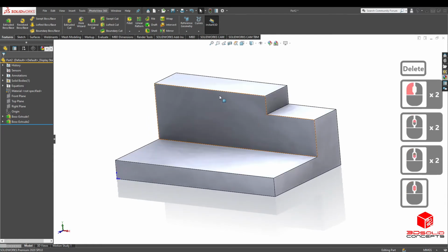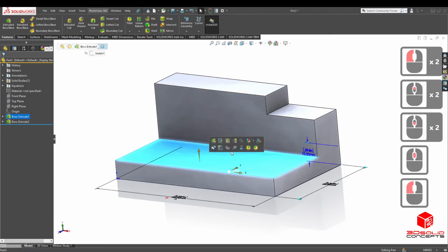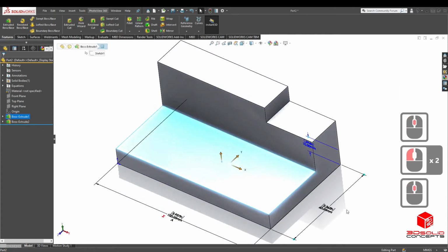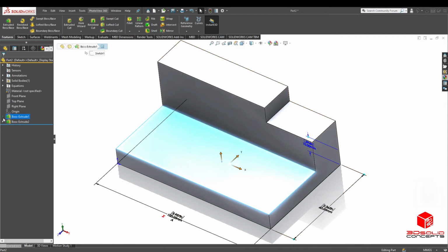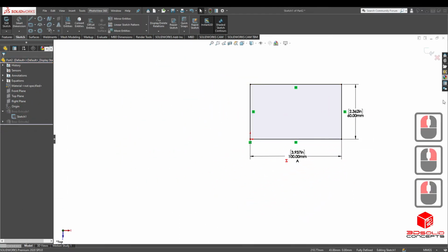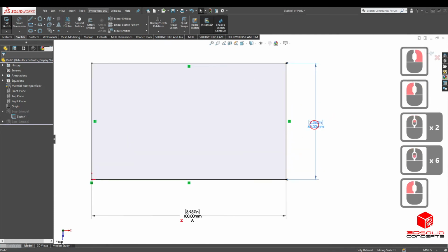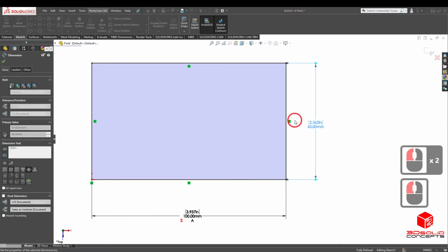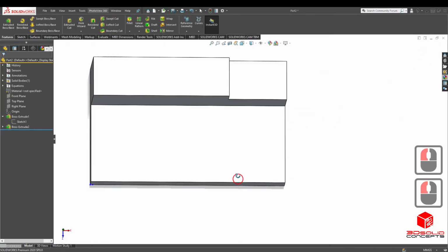And let's say you made a sketch and you want to change your sketch somehow because you put the wrong dimension. You click your bottom plate and you notice, oh, I put 70 instead of 60. So what you could do is click this down arrow, right click, and edit sketch. And now you're able to go back, double click that, and make sure you input the correct value. Press OK, and it'll automatically update.